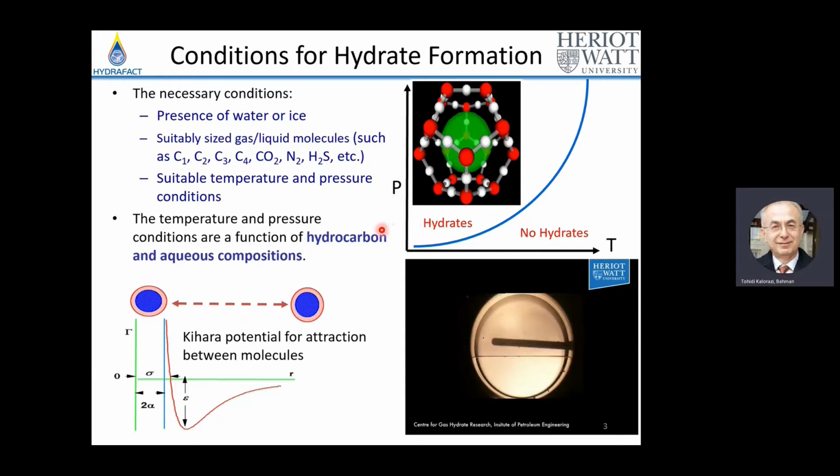We use this technique for preventing hydrate formation by injecting glycol and alcohols. Glycol or alcohol dissolves in water. Some water molecules will be busy with the solution of this molecule. Therefore, fewer water molecules are available for hydrate formation. So this is a common technique in the industry to avoid hydrate formation.